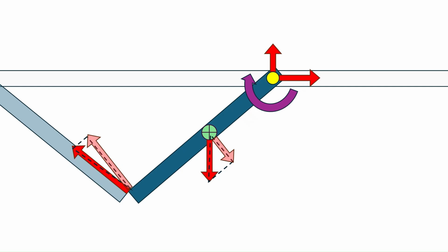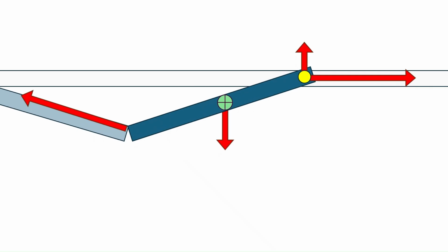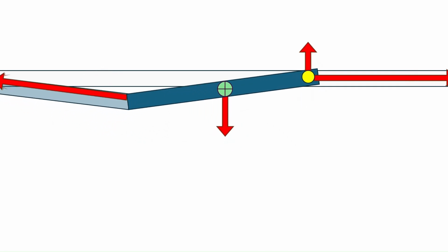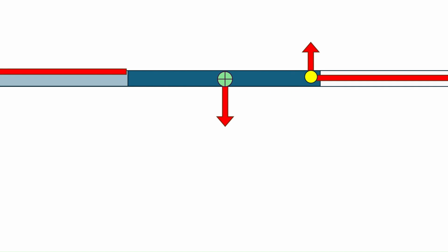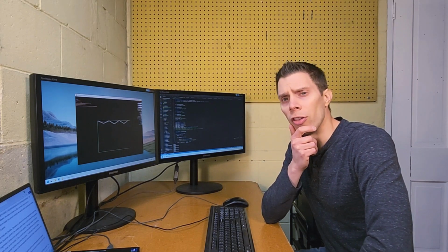But as we continue to rotate the panels flatter, because the angle between them is closer to 180, we need more force to generate the same orthogonal force to counter gravity, because gravity is closer now to a right angle, and we will generate a smaller torque. So in order to flatten the panels entirely, we would need practically infinite pulling force on that wheel. The physics says it's not going to work. So I need to come up with some design alternatives to make this feasible.